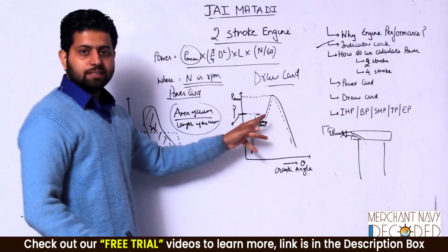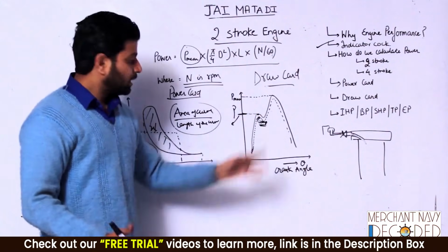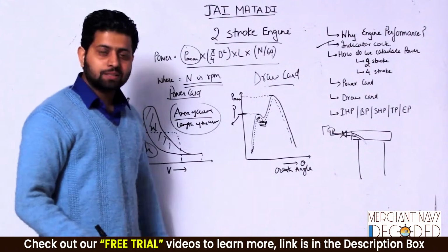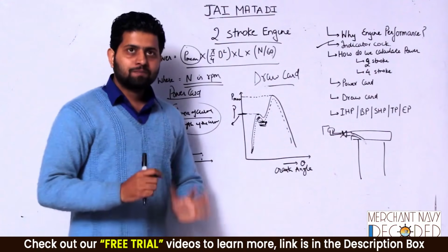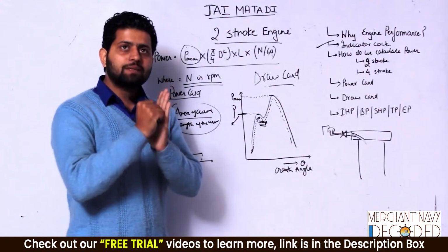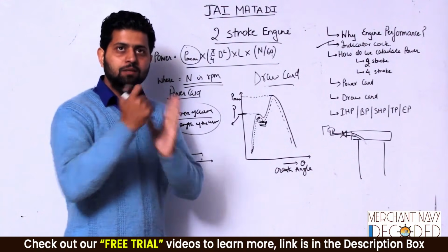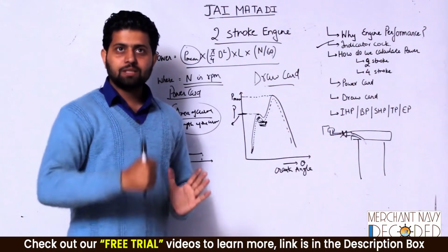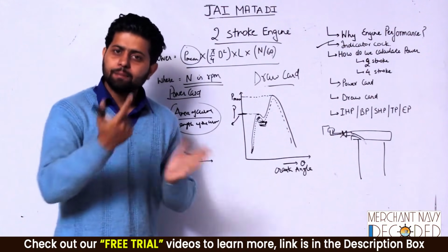First of all, this has got less now. After that fuel is being injected. If this is less, automatically this is going to be less. Now P compression is less. That means my air is not developing that much pressure when it is being compressed. So maybe scavenger pressure is less. Maybe air inside coming is less.